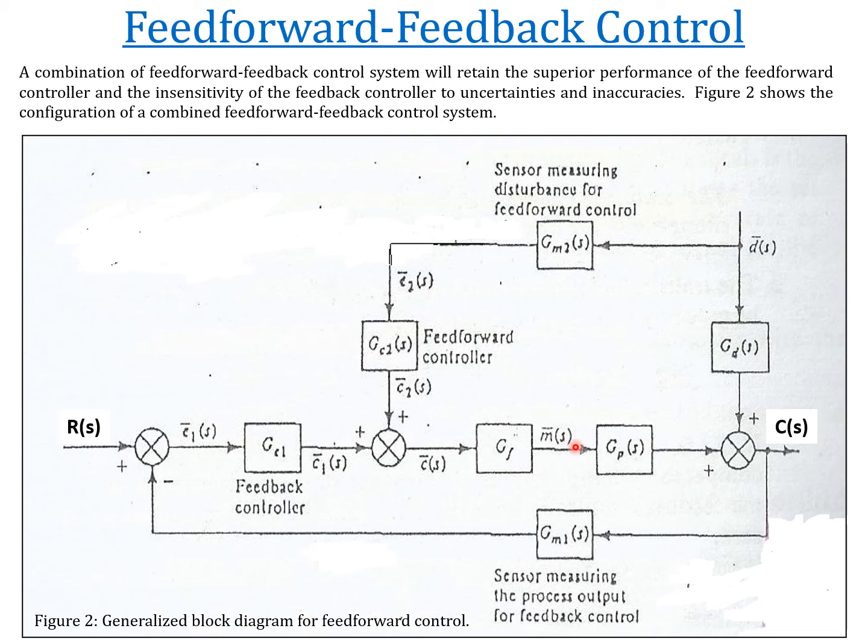And so what does it mean? It means for systems that are not so complicated, not so complex, you should be able to get a good model, and definitely that means the feedforward part can work very well. If you combine this, even if the model is slightly off, not so accurate, you still can take care of it by the set point, the feedback part. So of course, the feedforward may not be that accurate, but the feedback will take care. So at least the set point tracking will be quite good, but the disturbance part may not be good if the model itself is not so good. So that part we have to look into and cater for.